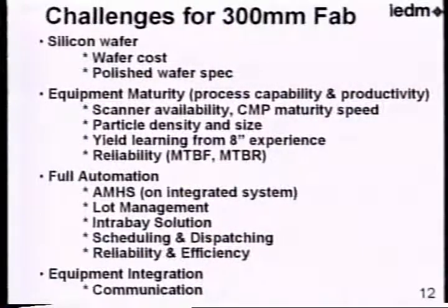All right, and how about the common challenges for all of us? First of all, is the silicon wafer substrate itself. The wafer cost is still quite high. A brand new control wafer can cost more than 10 times, several $100s, compared to an 8-inch control wafer.